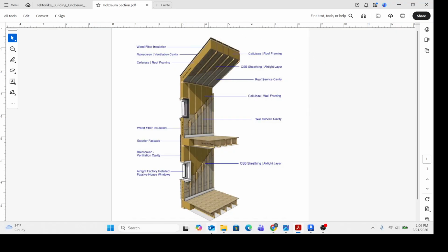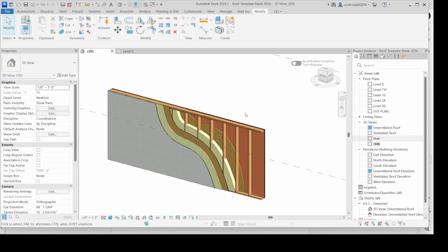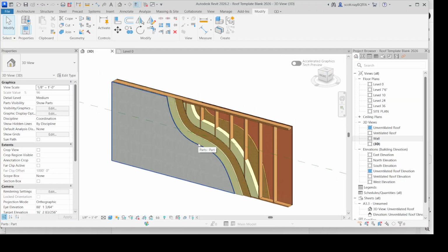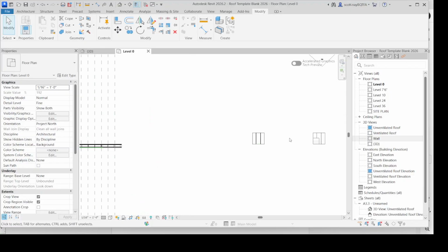But let's go back into Revit for a second. So after I finished, this is what I ended up with, that wall. I had to freeform this one because I ran out of model lines and it wasn't letting me do the offset because this curve became problematic. And then I just copied it and made its own layer because this is eventually also going to end up in your midterm. So what I want for our next one is I want to start by copying one roof and the wall into that file so that I don't have to redo all that work.